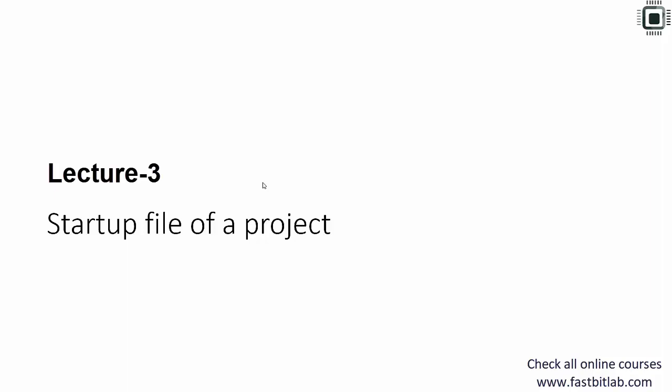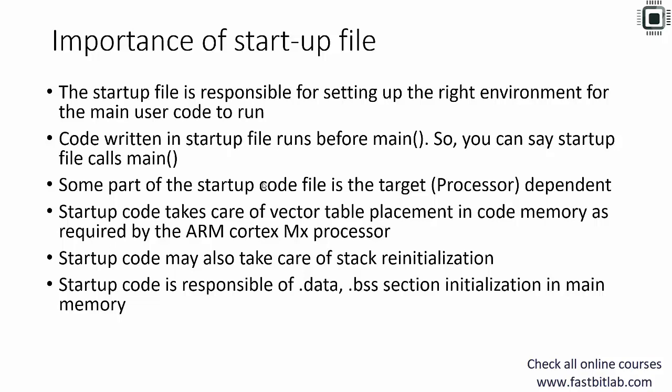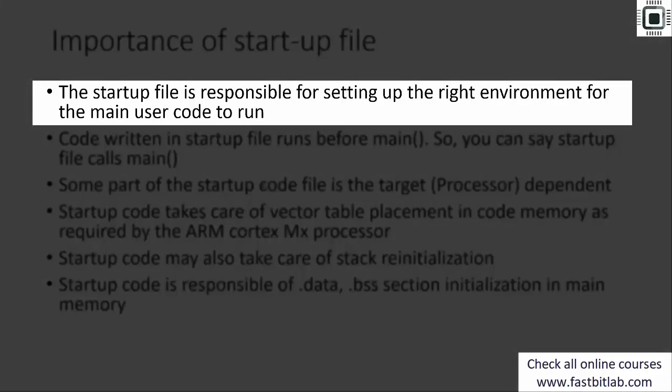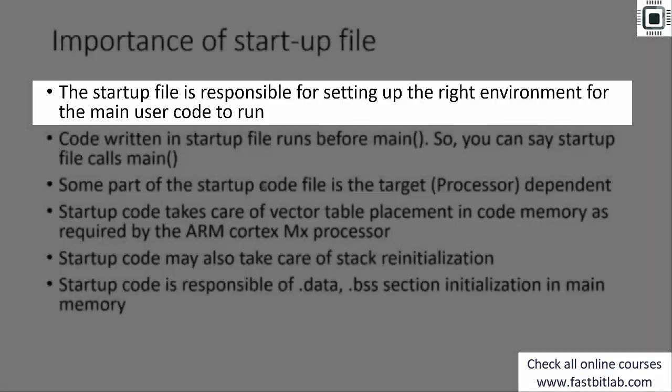In this lecture, let's understand the startup file of a project. First, let's understand the importance of the startup file, and later we have to write our own startup file for our project. Why is a startup file required? The startup file is responsible for setting up the right environment for the main user code to run.